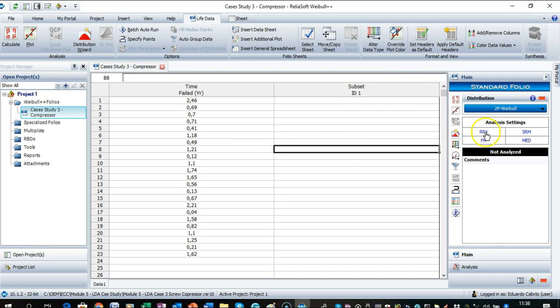And then we proceed with the lifetime goodness of fit test. So we are choosing the rank regression. You can see that we can choose the goodness of fit method that we are applying here. The basic difference from maximum likelihood is that maximum likelihood can be applied for all types of functions, but its result is much better when you have larger quantities of data.